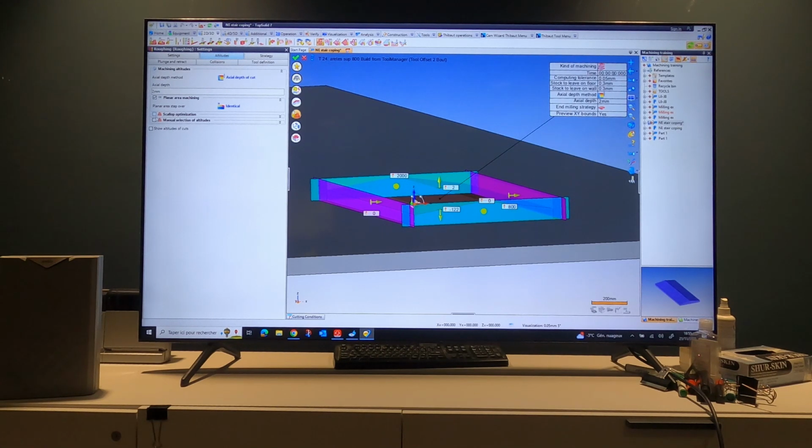If we define a step every 5 millimeter, we cut the model in 5 millimeter slices and calculate the toolpath in each one. If you have any flat area in between the 5 millimeter steps, just in the middle or somewhere, you don't make it. So then we add a specific path to that level to make the flat area. Then you save time for the next operation.